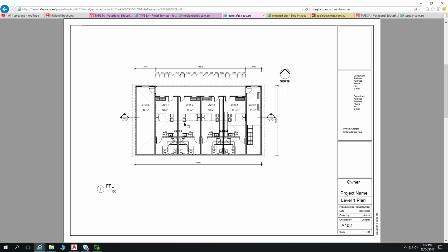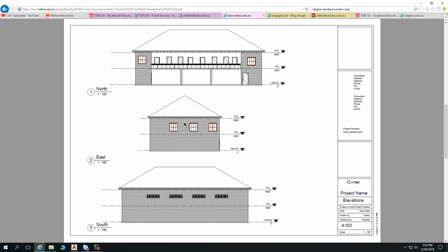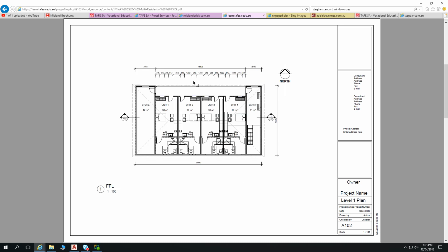Then we have 4 units above that car park, each with the access and balcony at the front. So very small bedsit units. A very inspiring external aesthetic. What you'll notice is we've got columns at the front here, so the building has columns. You can take them out if you want to. If you go, oh, we can do a fantastic floor system that can span that distance, by all means, take them out if you wish, but you've got quite a span there.